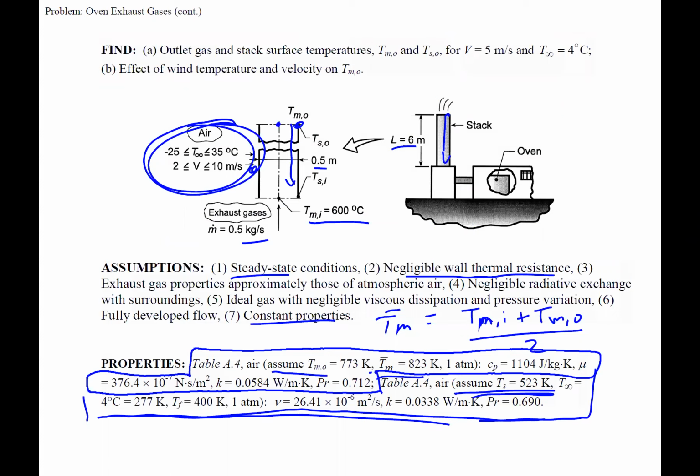Okay, so I do this in my studies. I have to keep everything where I take an exhaust sample greater than the temperature that the water would condense out, so that water doesn't condense out and change all my readings of what that exhaust sample looks like, because I wouldn't have the water in my sample if it's condensing out. So that's one of the things that they kind of look at, and that's the practicality of something like this.